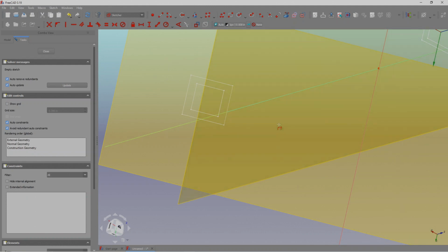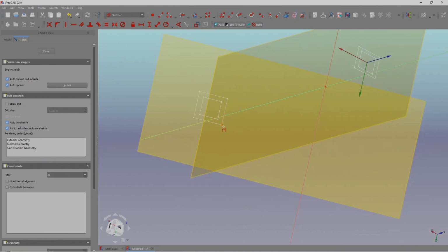Okay, it did that. It picked that vertex and connected it to this sketch. That's why it highlighted in red. I want to do the same thing here. Let's try to do that. Okay, so I was able to successfully do that. Now I can use this, because those 2 vertices are in this sketch. I can pick on them and draw something.